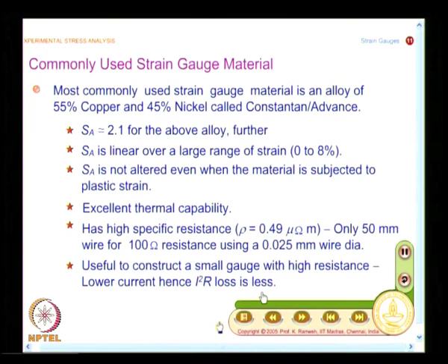See, I said in all strain gauge instrumentation, you will have to keep looking at the thermal influence. When current passes through the conductor, what happens? The conductor gets heated up, and you call that I squared R loss. If you have looked at my statement very carefully, I had said with the advancements in composites, people have developed 300, 350 ohms, 500 ohms, 1000 ohms, 3000 ohms, etc. And whatever heat is generated on the strain gauge has to be dissipated away.